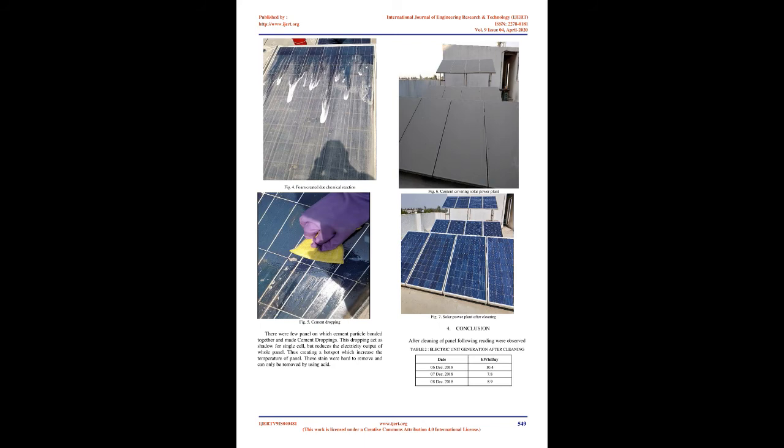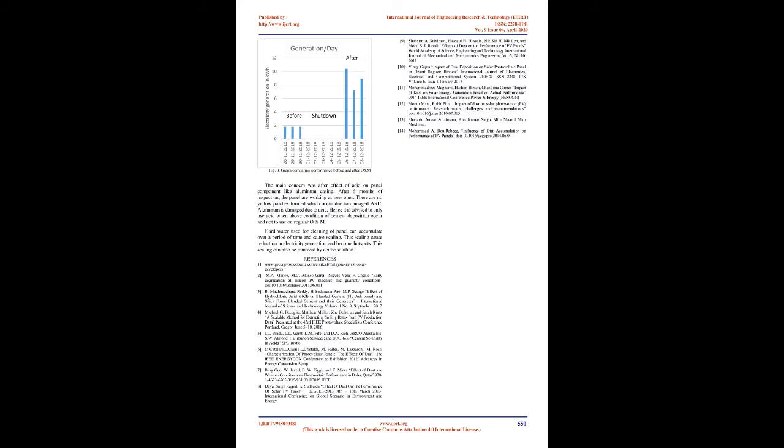E. Data collection. To compare and evaluate energy and power output between cleaned and cement-deposited panels, data was collected for 3 consecutive days. Cleaning of the panels required great care, as no pressure can be applied or it will crack the solar panel. The method used is the same as acid etching concrete. The acid solution was 60% concentrated. Using it directly would have reacted with the ARC and damaged it.